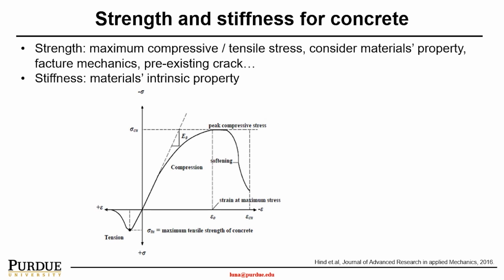First, concrete has very minimal tensile strength. As you can see, the ultimate or maximum tensile strength of the concrete is very small. On the other hand, we can see the peak compressive strength compared to the tensile strength can be different by an order of magnitude. Another thing is that concrete has more fracture behavior. As you can see, the strain has very small deformation.